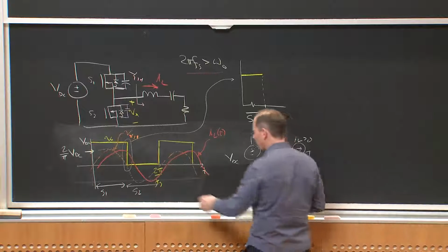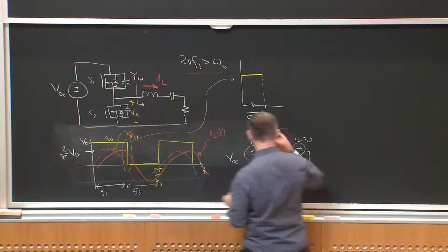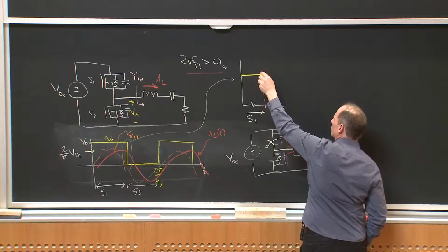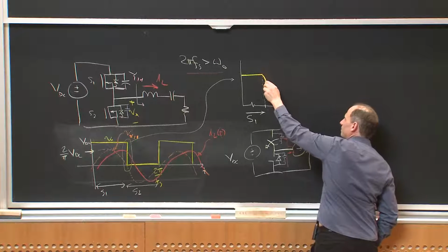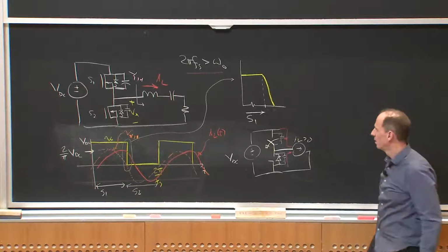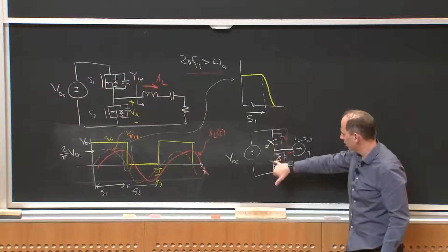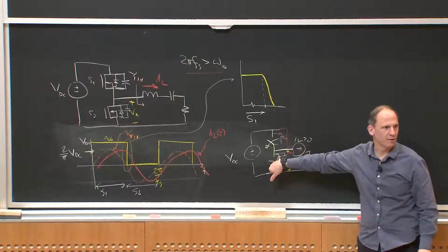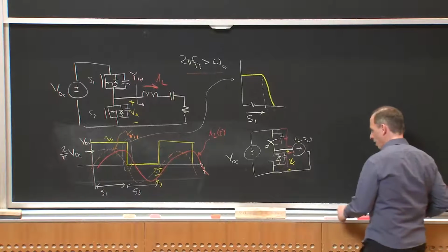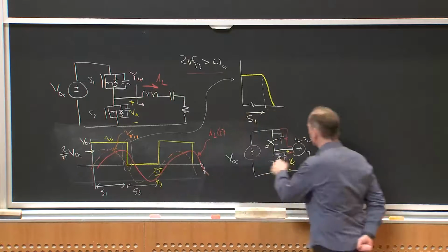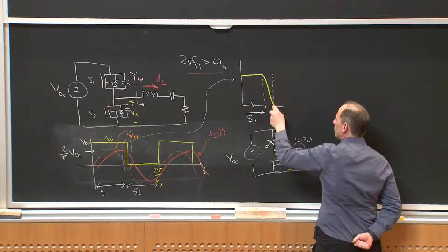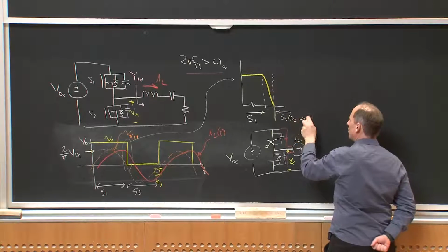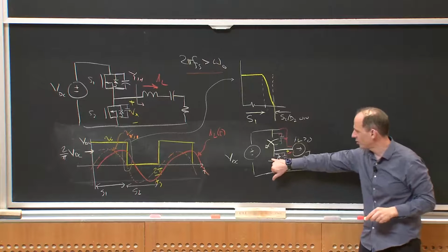So then if I were to look at this voltage, I'm going to zoom in right at this time period when I have both S1 and S2 off. What I'm going to see is a transition that's going to do something like this, okay? And then when this voltage hits 0, and this is voltage Vx, the diode's got to turn on, right? So if this was S1 on, even if I don't turn this bottom switch on yet, when this hits 0, I'm going to get S2/D2 on, right? The diode will turn on naturally, and then I can turn on this switch with 0 voltage.